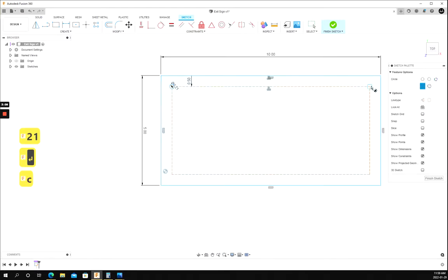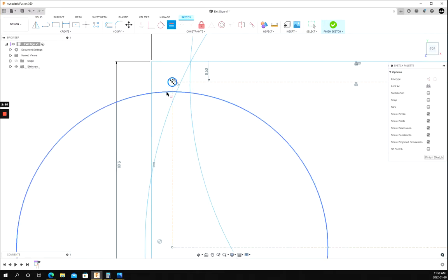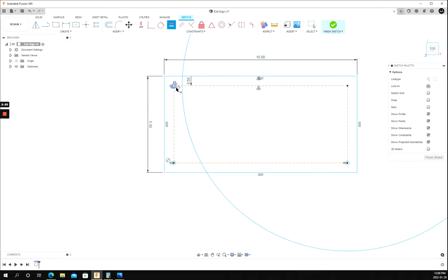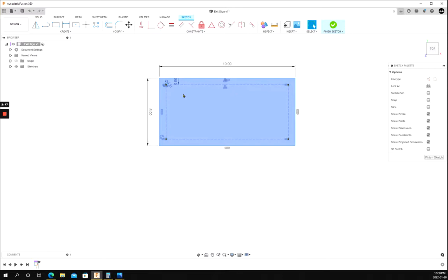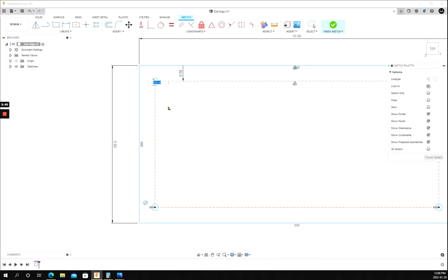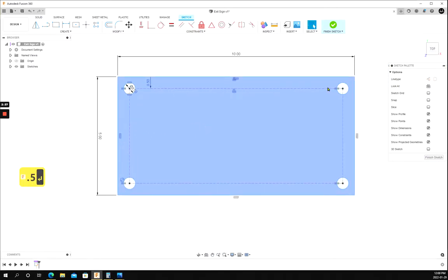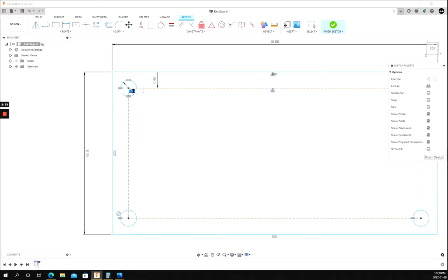Now for the rest, I'll pull the diameters out near the first hole, making sure to locate the centers correctly. And now I will use the equals constraint to make them all the same diameter. The reason I would do this is so if I want to change the dimension, for example here, I'll change this to 1/2 inch, it will change all those holes with the equals constraint on them. And now I can change that dimension back.